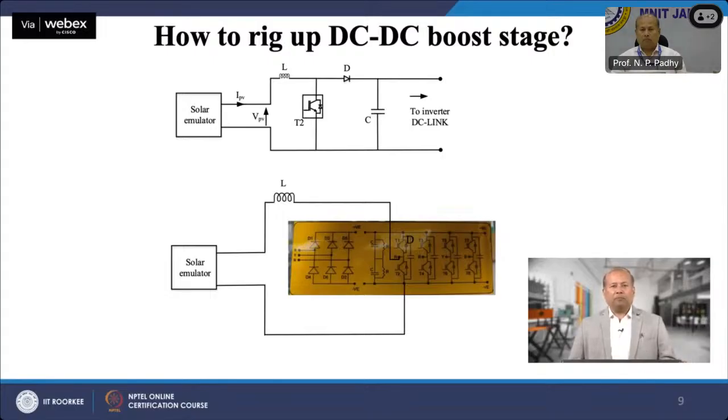We can connect positive terminal of PV input to an external high frequency inductor whose other end is connected to the point N. The lower side IGBT T2 can be used as switch which is connected between point N and DC bus negative.